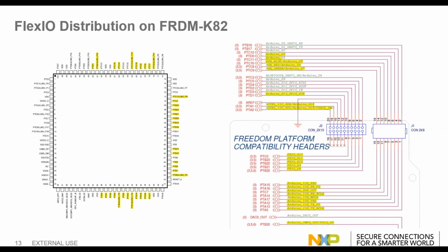You can see all the pins highlighted here on the top, on the right, and on the bottom within the pin multiplexing, which is the options for the outputs of these pins. You can set FlexIO signals. There being 32 FlexIO total signals available on this K82F MCU, these are the ones that are actually available on the 100 LQFP version.